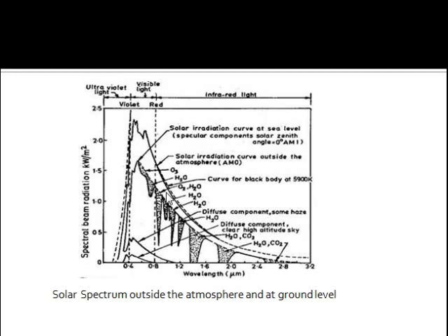What you can imagine from this is, radiation has energy which will be absorbed by the atmosphere. Finally we will get not 1.3, we will get only 1 kilowatt of energy per unit area. And if you go 1 kilometer above the sea level, then the energy content that any solar device on earth will receive is 1.05 kilowatt per meter square.